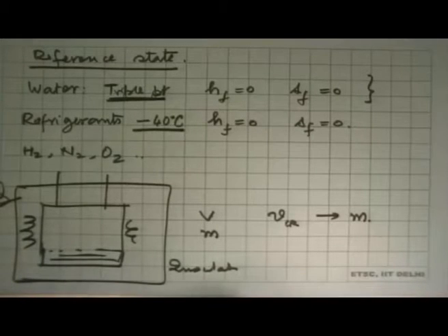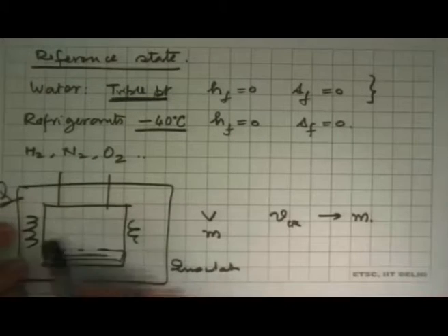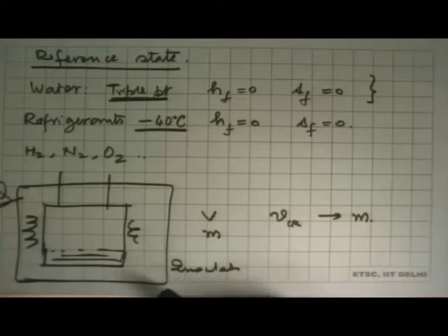The critical state, at least mathematically, looks like a singularity, which it is, and at that point, almost all the equations that are developed also start ill-behaving as differential equations. So now there is a belief that yes, critical point is there, but to exactly get to that pressure and exactly that same temperature and say that it is at the critical state, even within the experimental uncertainties, it's very difficult. But this is the way one would produce a critical state in a substance.